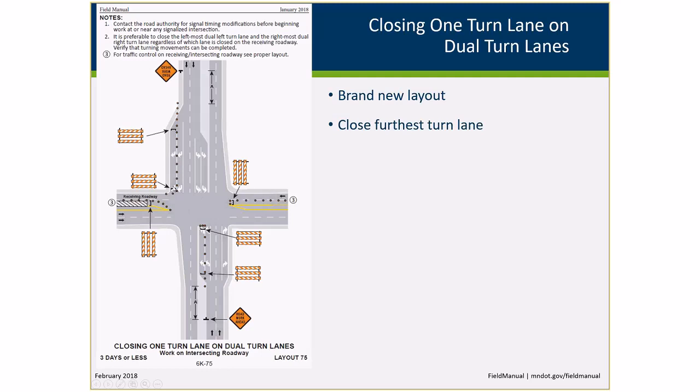But if you've got a dual right coming into it or a dual left coming into it, we're saying that you really should close one of those lanes in order to make it so that when the traffic comes into it, it's only a single lane of traffic that's coming into it, and they're not trying to merge as they're approaching that work zone. Because if someone's not letting someone else in, where else can they go? So that's the challenge here. So this is the layout that was developed for it.